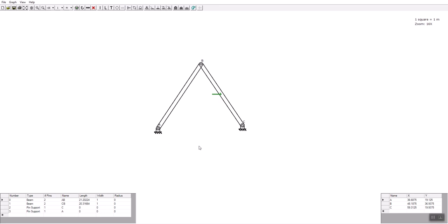And now what happens is that this pin actually can apply force in any direction because this pin applies two components, horizontal and vertical, and these components can rearrange among themselves, so the support force is along AB. So this structure should be solvable. So let's go here.